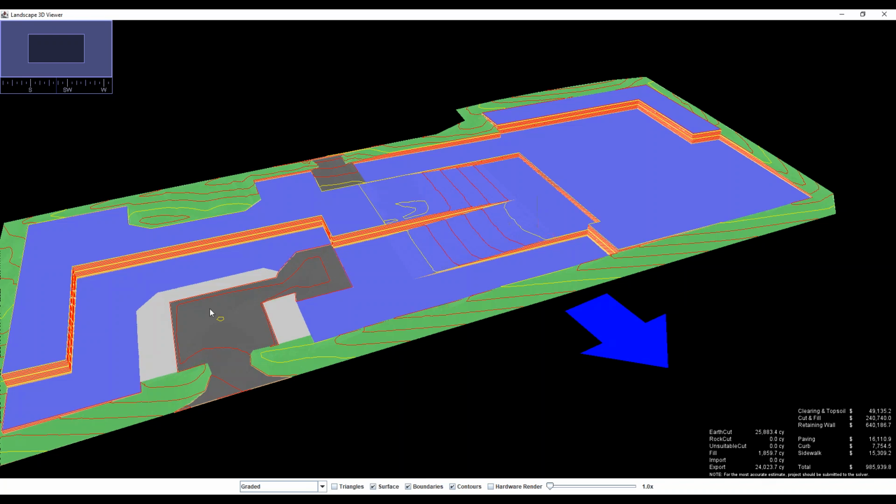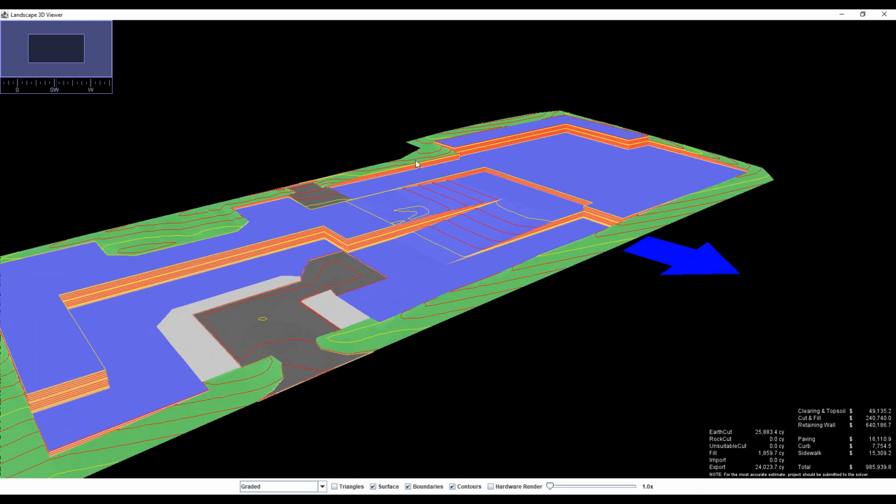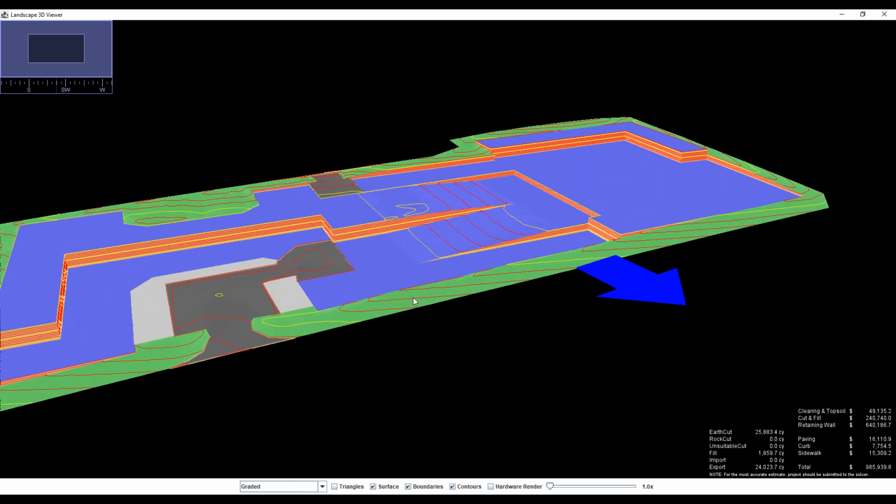And even on this one, this is one where they forced elevation on us, and we go back and show them, like, hey guys, you're burying some of your units over here and over here, you know, and this is, you know, what if we come back and lift these slabs up a little bit? Now we can start getting back to a more balanced scenario.